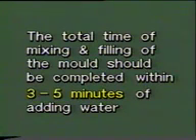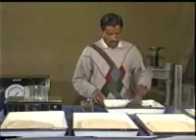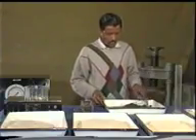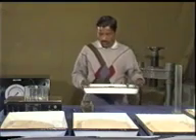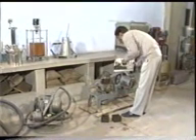The total time of mixing and filling of the mold should be completed within 3 to 5 minutes of adding the water. Place the mortar in the clamped mold through hopper on the top.